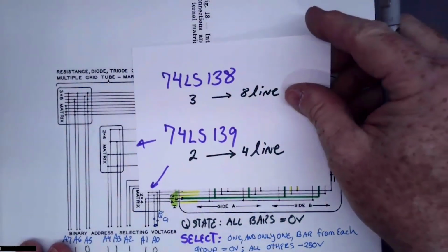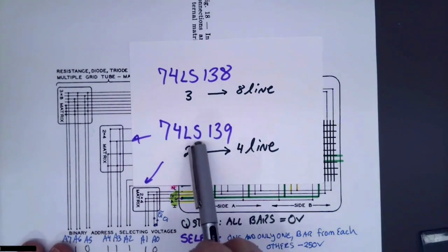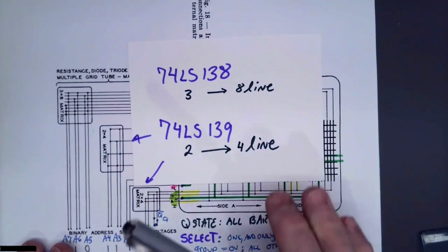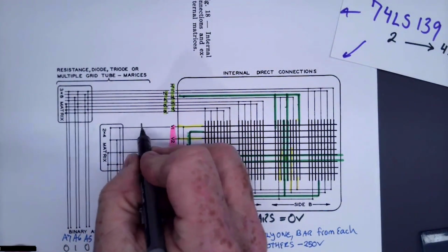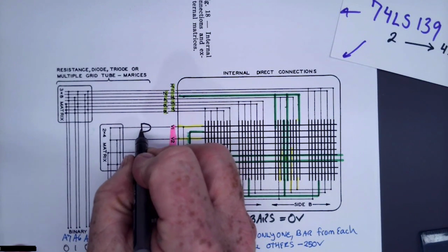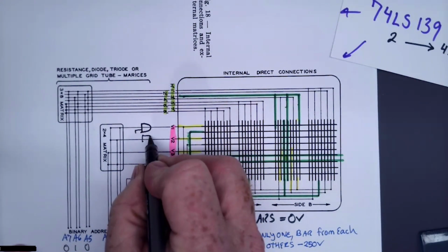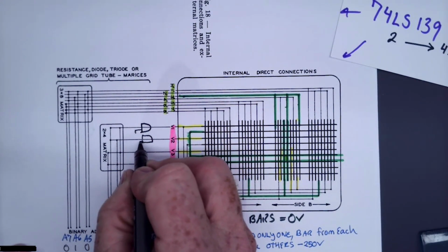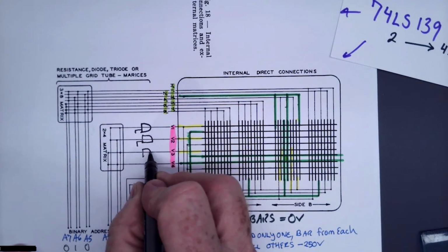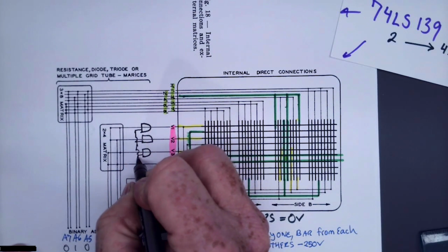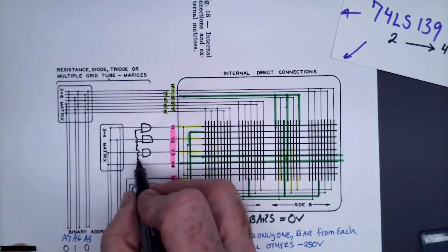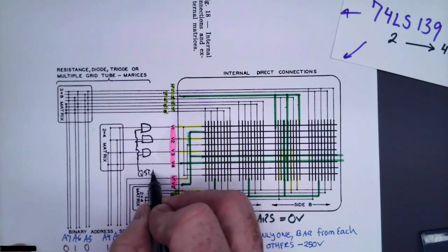When we build a circuit, these guys right here really are just going to be these 2 integrated circuits. It's simple as that. But I need to add some gating on this so that whenever I want to be in the idle state, everything is 0 volts. So what I'm going to do is basically add an AND gate to every line, every single one of them. There's a bunch of bars here. I didn't draw that so well. AND gate. So every one of these guys are connected together, and I'm just going to call this my Q state.